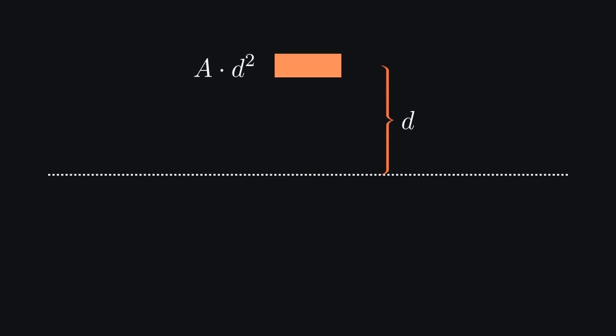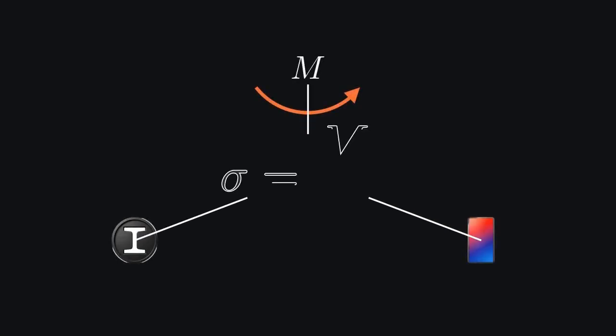Economic sections push material to the extremes to maximize strength and minimize unnecessary weight. Second, the parallel axis theorem quantifies the exact structural advantage of moving that material away from the center. And third, the flexural formula acts as the absolute mathematical link between the shape of a beam, the applied moment, and the resulting normal stress.